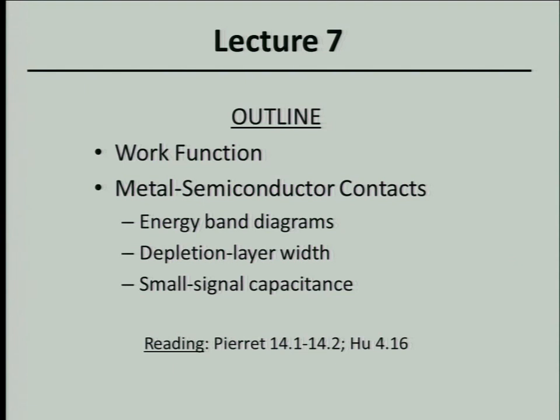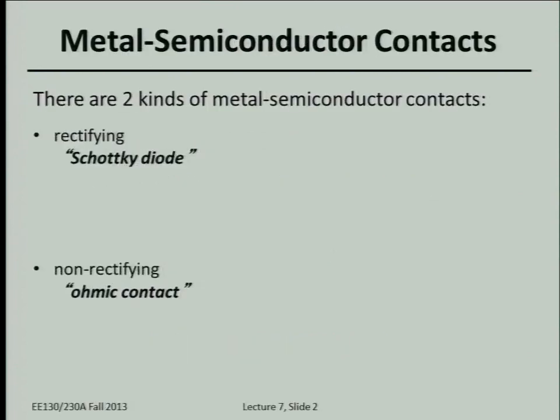I'll tell you right now, you might remember it later, that for some of the advanced semiconductor materials, it's not easy to dope the semiconductor to make it electrically very conductive right at the metal contact. For that reason, you have very large resistance to current flow across that interface. So even if you have a very high performance transistor material, if you can't get the current in and out effectively without wasting a lot of voltage dropped across the contacts, then you're not going to get the performance you want from the high mobility channel materials. That's why it is fundamentally very important to understand metal semiconductor contacts.